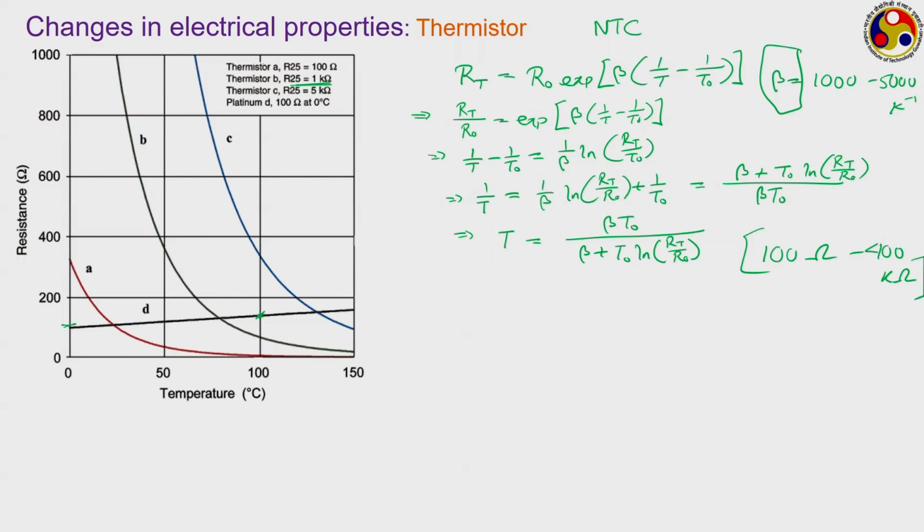Certain materials like doped germanium, impregnated glass, etc., can also be used in cryogenic applications as common materials for this. Their advantages are they are much cheaper than RTD, and they have very high accuracy and very high sensitivity, much higher than the RTD. If we compare, just look at the sensitivity expression we have seen, the rate of change of resistance with temperature divided by the initial resistance value.